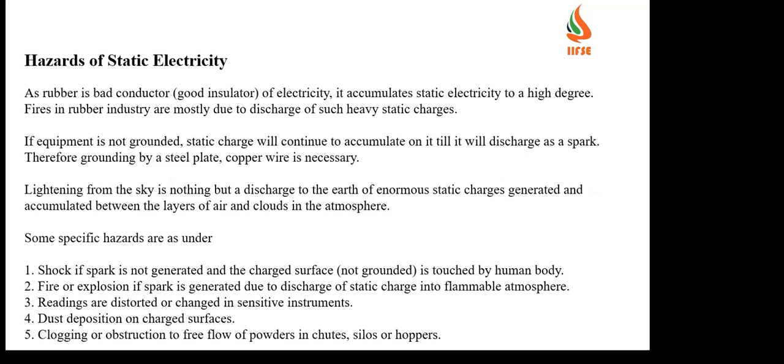Let's see some of the hazards. Rubber is a bad conductor, and we can also call it a good insulator of electricity. It accumulates static electricity to a high level. Fires in the rubber industry are mostly due to the discharge of such heavy static charges. So with fine rubber dust and rubber powders, it is highly insulated. The more highly it is insulated, the more it tends to accumulate static electricity. The more resistance it has, the more static electricity accumulates.